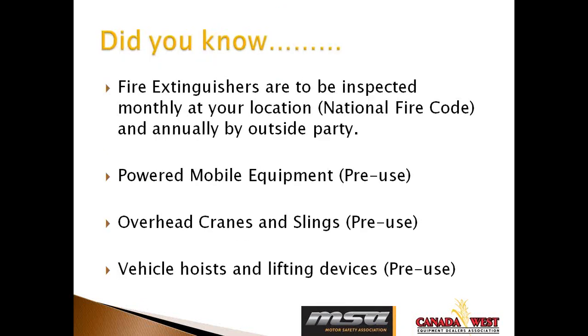A couple other facts that you may not have known when it comes to inspections: your fire extinguishers are to be inspected monthly in-house at your location. So that means you or someone at your dealership is responsible to take each fire extinguisher, examine it, make sure it's clean, check that the hose is on it, the pin is in, the gauge is in the green. You can take it off the bracket and you can tap the bottom of it with a rubber hammer to excite the molecules inside of it so that it's ready to go in case you need it.